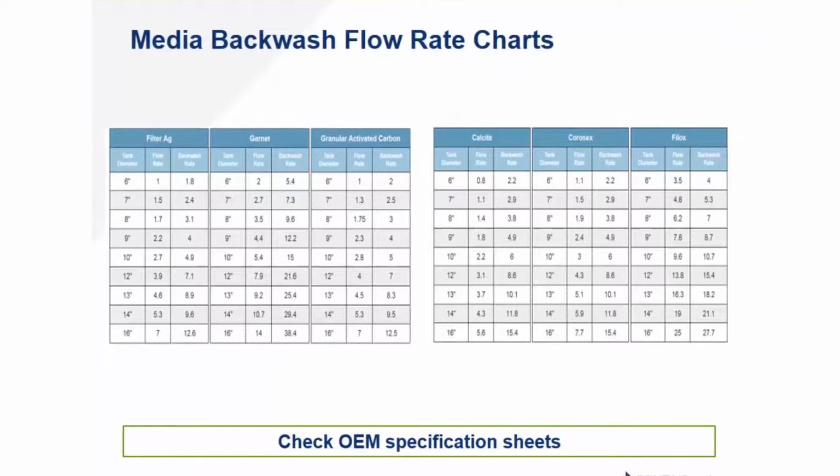It takes longer to get that bed to move and rise up in warm water, whereas in cold water, that lift happens readily and the chaos starts much quicker. So warm temperatures, longer backwash, because you need to do more scrubbing.